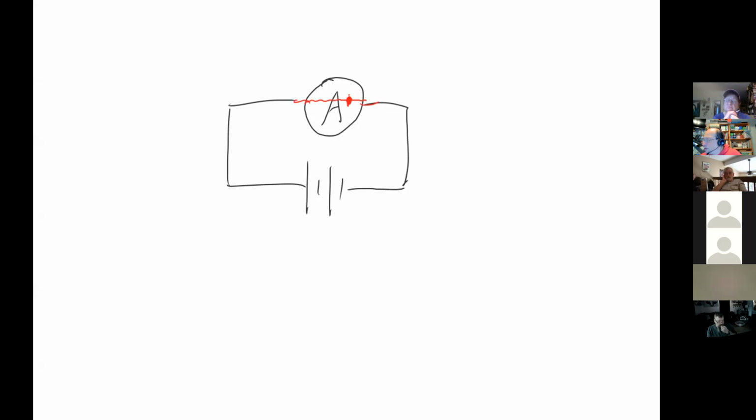So very often, somebody mentioned something about fuses. When I go and buy a Fluke multimeter, it actually has in the back of it a spare fuse, just for such an occasion when I accidentally hook it up to the wrong thing. Then it pops the fuse and I can go and buy a replacement $15 fuse for it. If I have a cheaper multimeter that doesn't have a fuse, what happens is that I do something called letting all the smoke out in a large cloud.